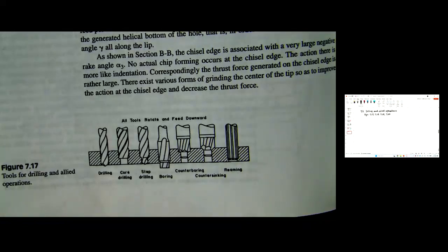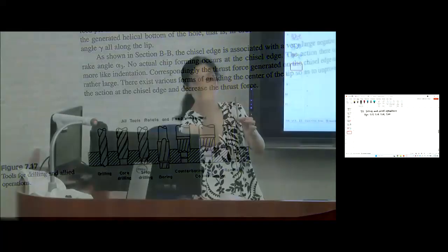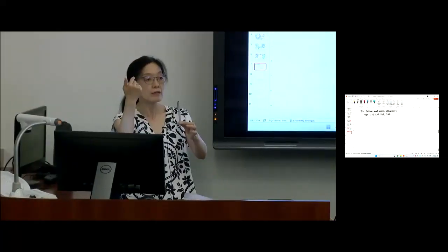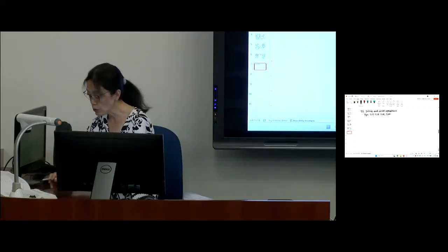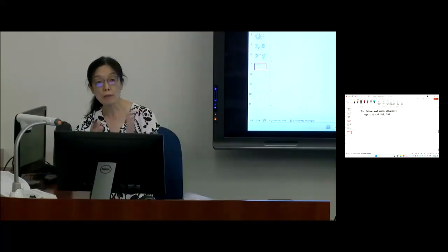that's the helix angle. It depends on what kind of material you machine, hard or soft, and then how the chip flows, how you are going to eject it. Because in turning, the chip is outside. In drilling, as you go in, the chip has to go out. So this angle, how many turns the chip has to travel, makes a difference. That's why it's changing. But for now, I just want to use this one, and then we watch the video, so you get a better idea.